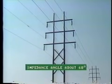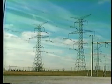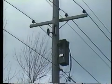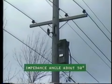The line impedance predominates, and for a 115 kV transmission line, this is usually about 60 degrees. High voltage lines, 230 kV and up, may have impedance angles as high as 85 degrees. Conversely, low voltage distribution lines usually have a line impedance angle of about 50 degrees. Well, now let's move on to look at the conditions for a phase-to-phase fault.